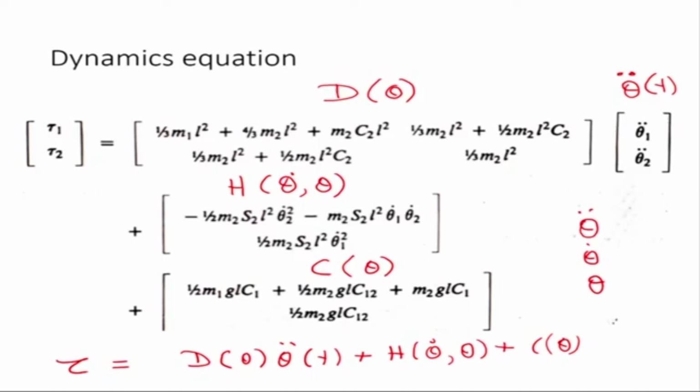So if I want to find what are the torques acting at the joints, I have to supply the joint position, velocity and acceleration at different instants of time. And for doing that, I have to fit a trajectory onto these joint angles, which will take it from one position to another position. Okay, so essentially, in order to do the inverse dynamics of this equation, you also have to generate a trajectory. So you have to do trajectory planning also.